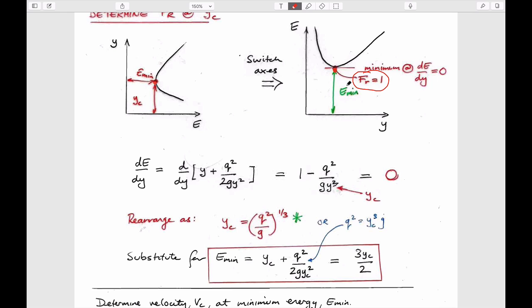So we said that this boundary between supercritical flow and subcritical flow, the physical explanation of it was that at supercritical flow, the flow is moving downstream faster than the celerity wave velocity. So like a drowning person flapping in the water, if you're trying to signal by sending a wave, it never gets to the recipient upstream of you. So there's no information sent upstream. So the point of the flow, the flow rate in the river that gives you that is this value, F equals 1. At places where it is subcritical, the Froude number is less than 1,